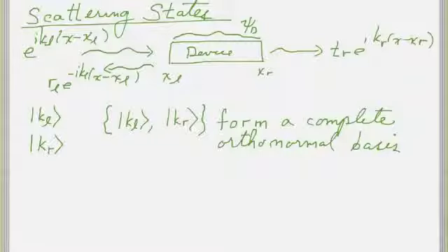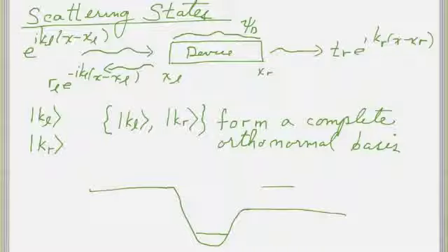The only exception to this is when you have a situation where, say, this is my conduction band in the left. It's supposed to be flat, sorry. Here's my conduction band in the right. And in the device, if I have a situation like this, with some state down here, that's a bound state below the continuum on both the left and the right. The scattering states can only account for all of the states above this energy here.